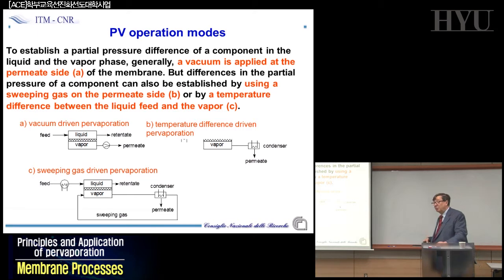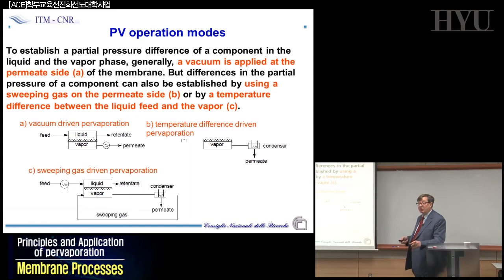There has been some confusion in the literature between pervaporation and membrane distillation. Sometimes you still find papers talking about thermal pervaporation, assuming it is something similar to membrane distillation. There is a basic difference: the transport mechanism is totally different. In pervaporation, you use dense membranes, and the mechanism of transfer is solubility and diffusivity.